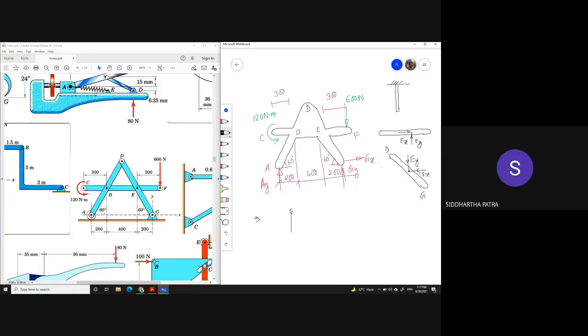If I am being asked to draw the free body diagram of the rod, I'll be showing a center of gravity, the weight coming from there, and then the reaction it is receiving from the support. Since at the support it's a fixed joint, I'll be showing Ry, Rx, and some moment reaction. But eventually, when I solve the equations of equilibrium, these two quantities would be 0.